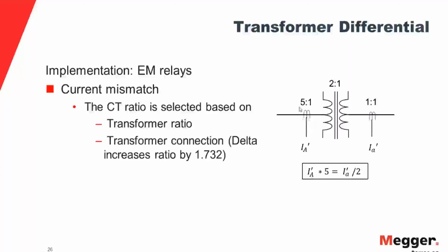The other challenge that I could think of is the zero sequence current. So for any external ground fault, especially for the Y-type connection on the transformers, you will also experience, or the relay will also experience, a zero sequence current. So how do we mitigate those challenges? Now let's first take an electromechanical differential relay or electromechanical transformer differential relay.